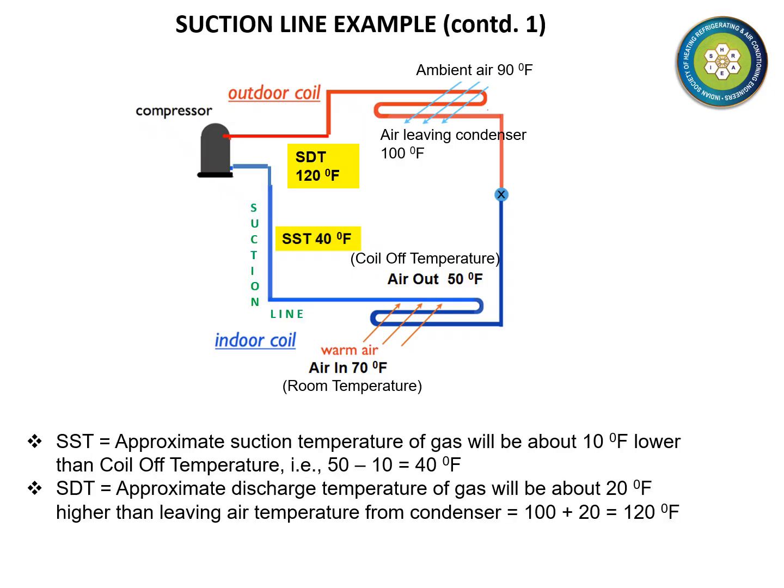The estimated value of SST, saturated suction temperature, is 40 degrees F, while the estimated value of SDT, the saturated discharge temperature, is 120 degrees Fahrenheit.